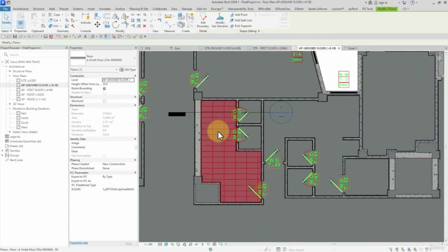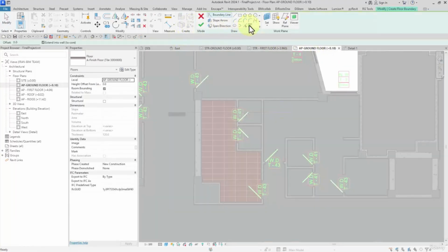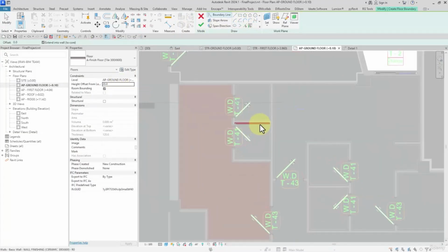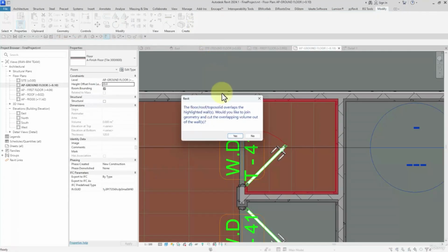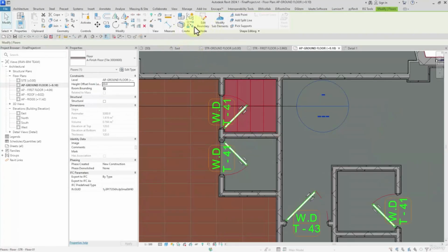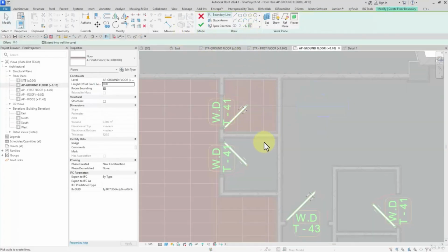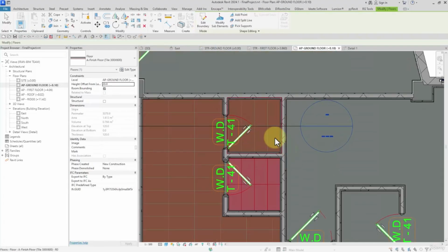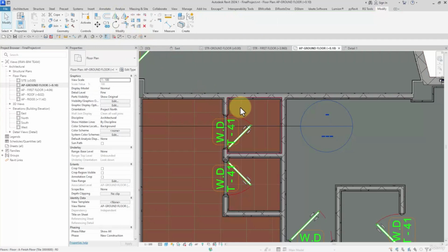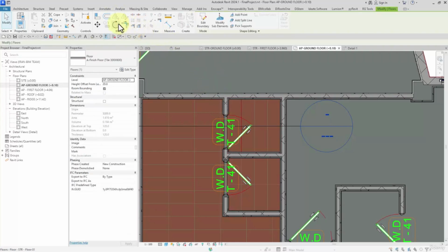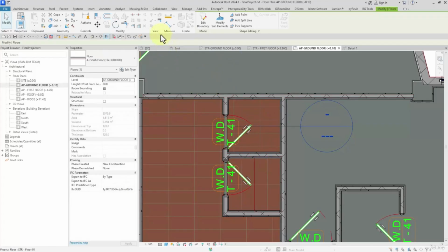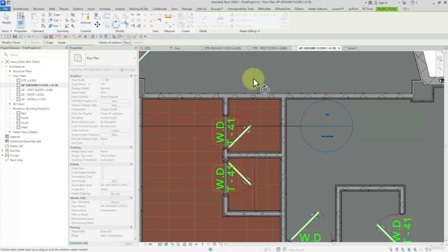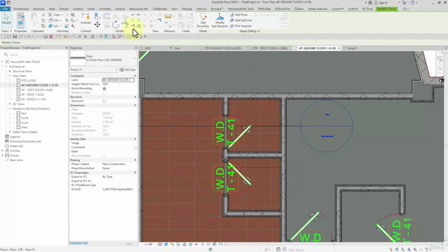And also for the vertice, we can select this, Create Similar, 2 centimeters offset. We press down Tab to select the boundaries, then click on Finish. Note that you have to create the floors for each of the rooms separately, one by one, and then, as I told you, I can select the patterns and then rotate them at 90 degrees, like this way, 90 degrees.